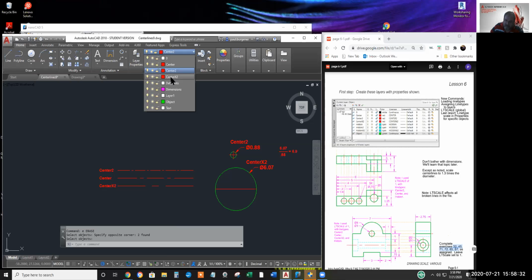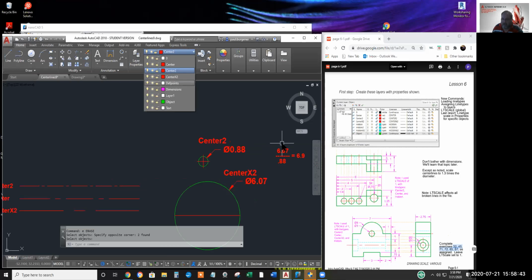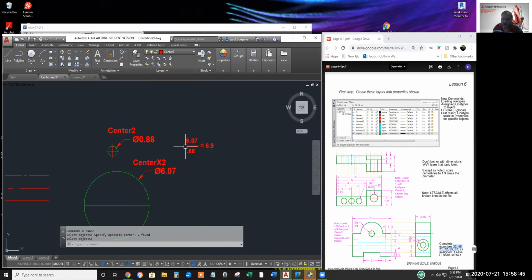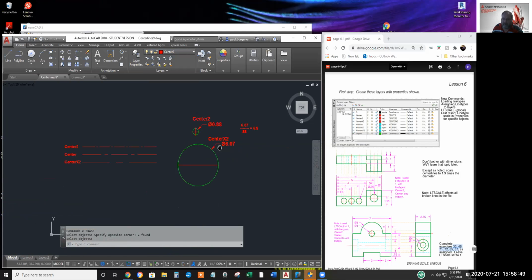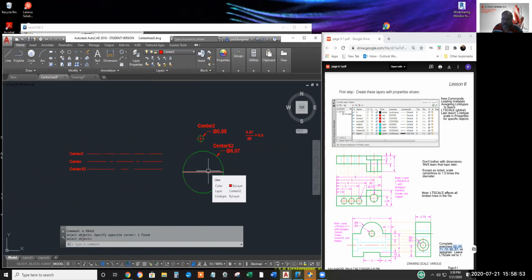If you've got a microscopic circle in the same drawing as a humongous circle, and they exceed this ratio of small to large, then you can go to the LT scale multiplier, which is a property of the object. That's the one I've been modifying.